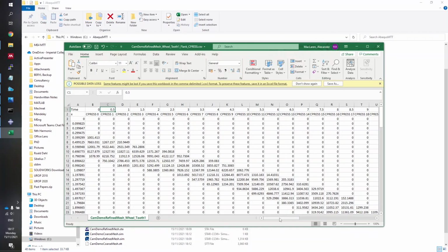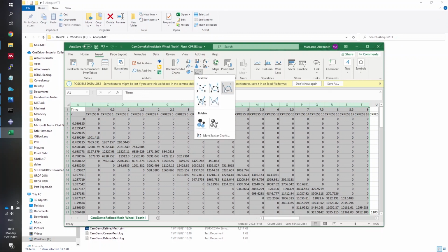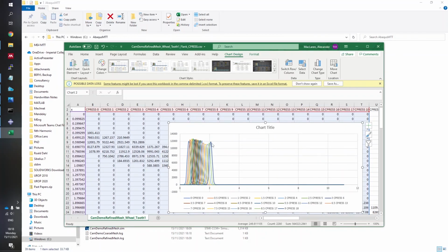And so each series on that graph we just had was time. And then in the vertical axis we have x. I should also say that because this is contact pressure, or C-press, it's actually defined by Abaqus not as a stress but as force per unit length. So you'd need to divide by the face width, which is 30 millimeters, to get a representative stress. If I just plot that again, we can see that the maximum values are of the region 12,000 force per unit length. So if we divide by 30, we get something in the region of about 400 megapascals, which is what we expect.